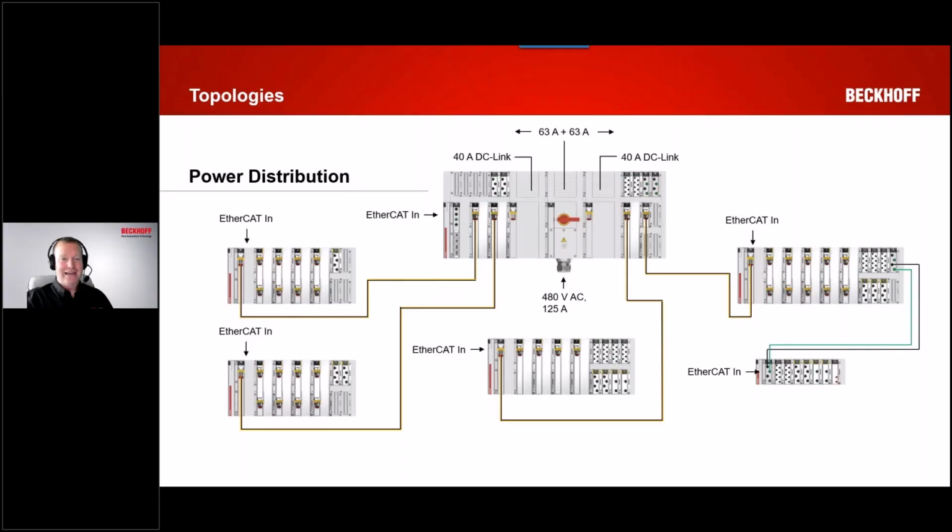And one thing to really highlight here is the way we're using these base plates. So you'll notice on a few of these, we have some empty slots that are just covered up, especially on the bigger base plate here. That's totally fine. We've got that EtherCAT communication chip on the board to say, hey, I know there's nothing here right now and it's covered. But we're also utilizing the second row to do some data communication in order to keep us from having to go another 4 wide and waste a bunch of aluminum and waste a bunch of space and that type of thing. So we have some versions of these that will work where it kind of wraps that communication around.